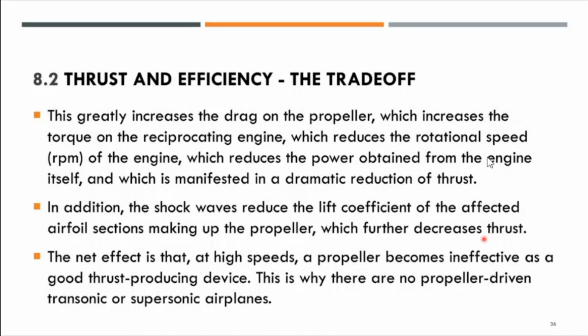So the net effect is that at high speeds, the propeller becomes ineffective as a good thrust producing device. This is why there are no propeller driven transonic or supersonic airplanes. That is one of the reasons it is not suitable for a very high speed airplane.